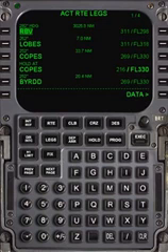The first thing the VNAV calculates for the descent is the top of descent point, TOD. This is the point where an efficient and comfortable descent begins. Normally this will involve an idle descent, but for some aircraft an idle descent is too steep and uncomfortable. The FMS calculates the TOD by flying the descent backwards from touchdown through the approach and up to cruise.